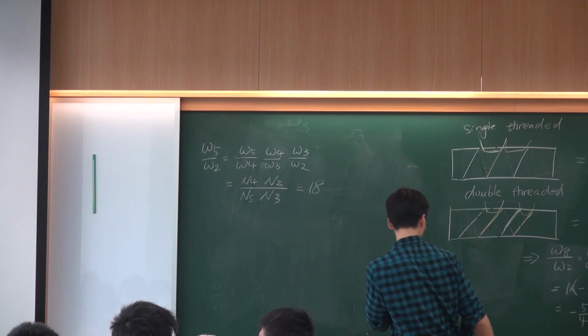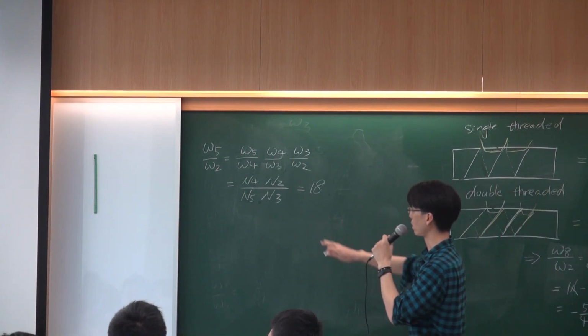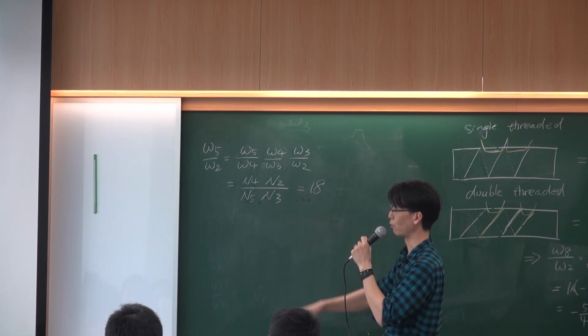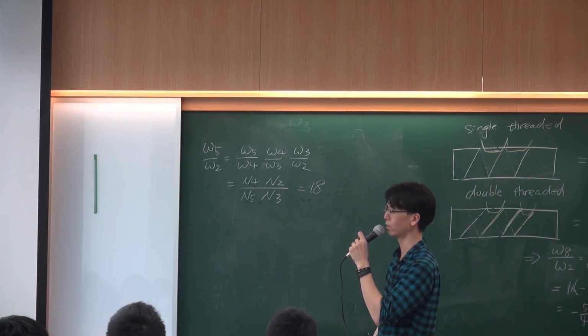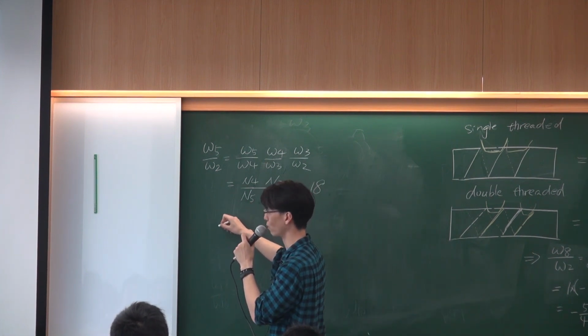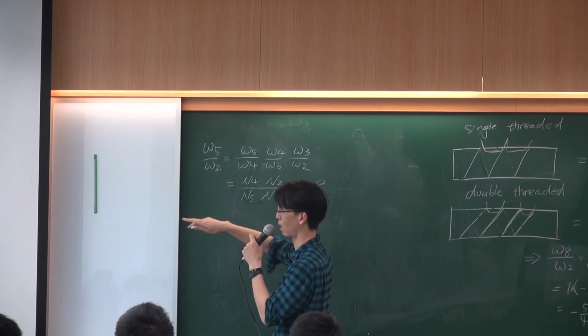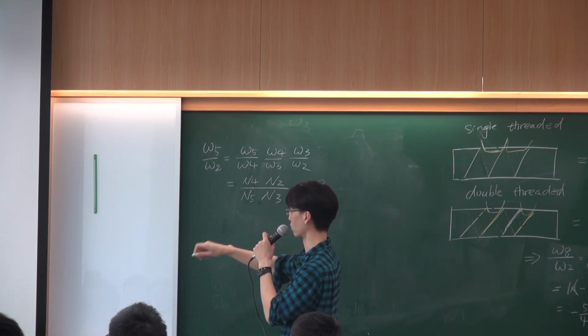That's a limitation. And so right now we get this gear ratio, but we know because right now it's a concentric gear reducer or concentric gear train, you need to follow another rule. That's R4 plus R5 equals R2 plus R3.